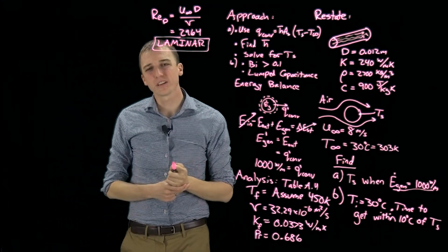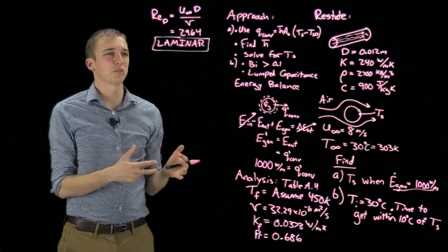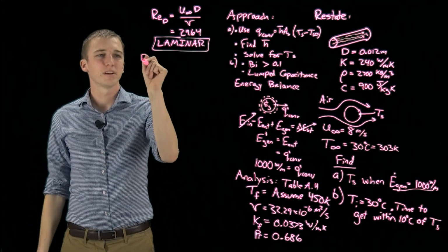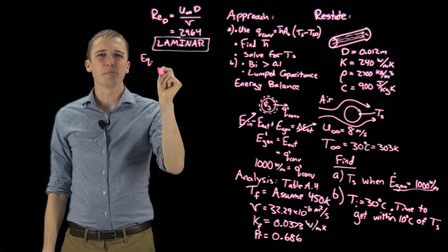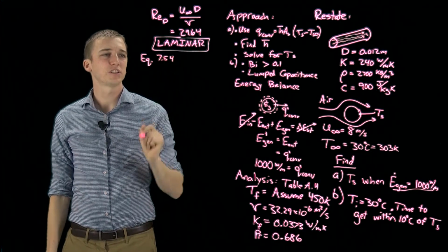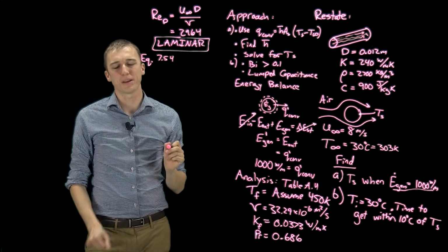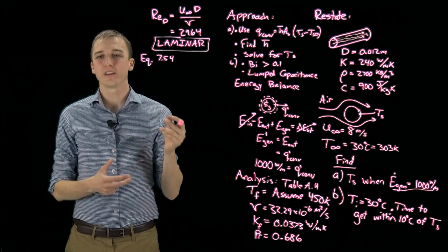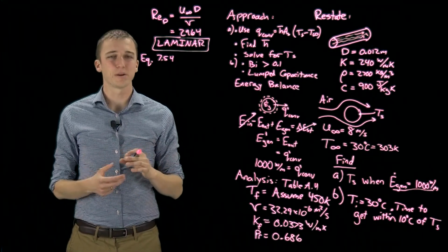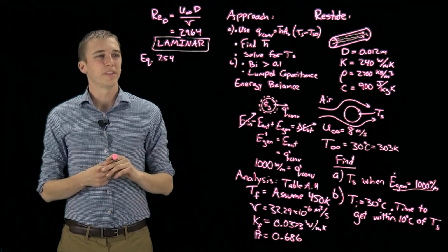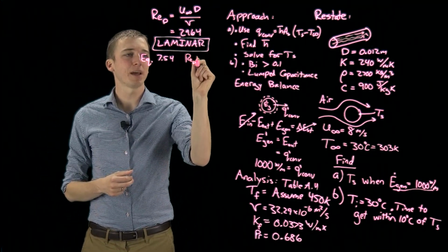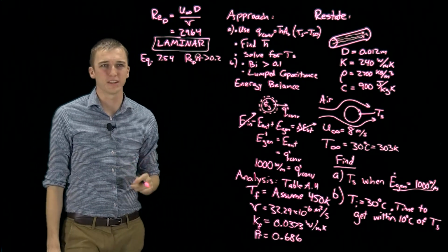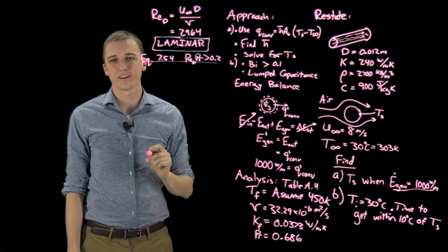Okay, so here I'm actually going to change the solution. I'm going to do it differently than the book does. So the book uses equation 7.54, the Churchill-Bernstein correlation, which is a fairly long and convoluted equation giving you the average Nusselt number as a function of the Reynolds number and the Prandtl number. That's nice because it applies for any Reynolds times Prandtl greater than 0.2, which of course we very much fulfill that criteria. So we would expect this correlation to be very accurate.